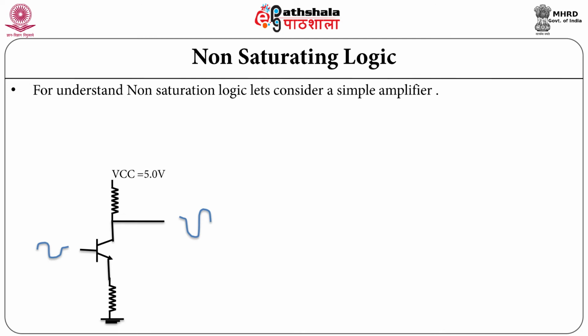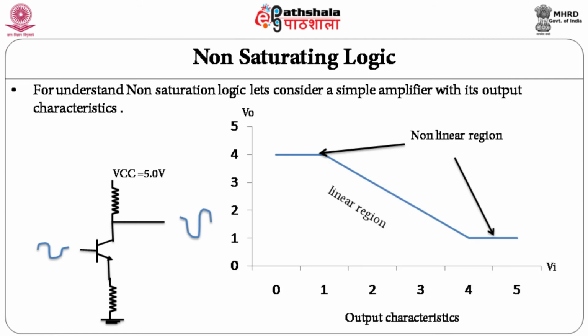When you use a transistor as an amplifier, it is operated in the linear region. If you look at the graph, you can see that there are 2 nonlinear regions and one region called the linear region. The nonlinear regions are the cutoff and saturation regions, and there is a linear region where there is a linear relationship between the input voltage and the output voltage.